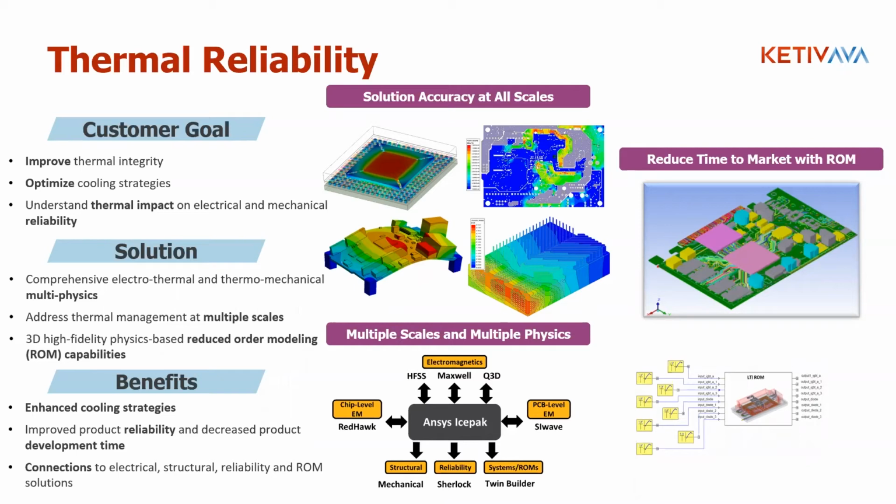It can then go to the next level of the PCB itself, and then also look at thermal reliability of an entire device, and model this by looking at the actual cooling flow, whether that's by convection in a fan or by conduction through traces and so forth, and allow you to really get a sense of where I have thermal reliability issues, where the hotspots on the board are, and how that is going to affect my design.